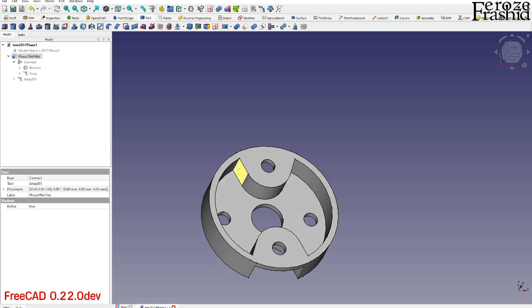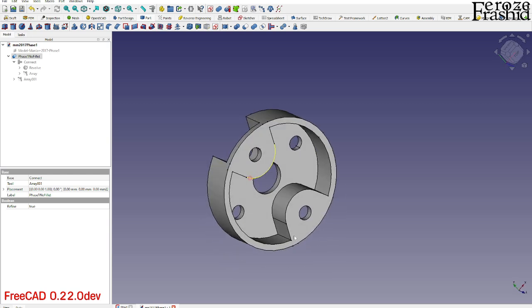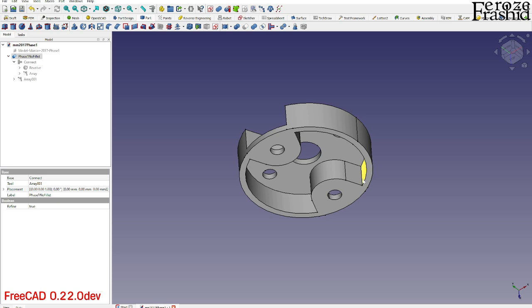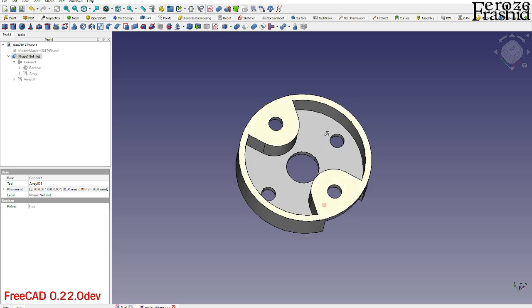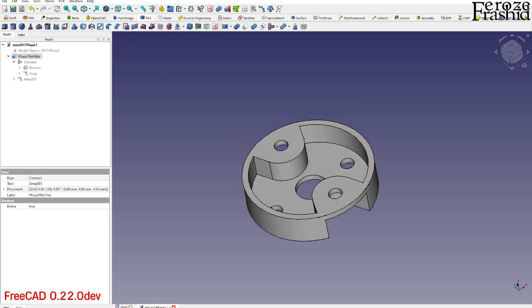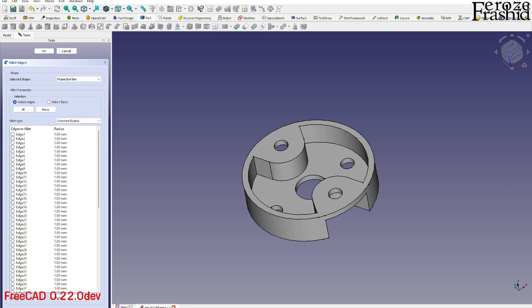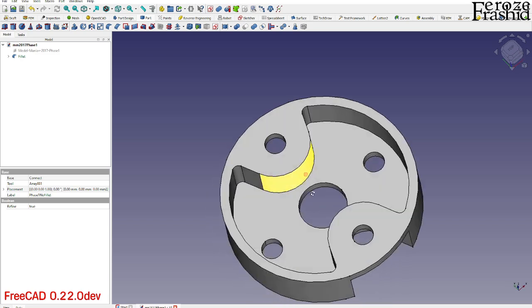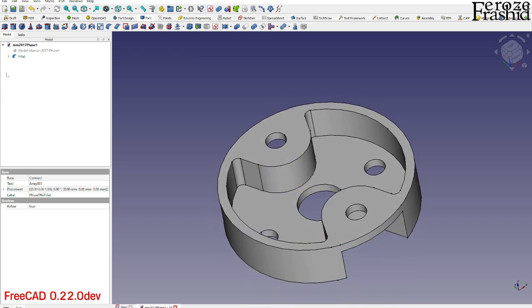a fillet. Okay. And come here, fillet, and I think it's 2 millimeter fillets all around. Yes, so make it 2. Let's make sure like we have all 4 edges selected. We have 2, yes, 4 edges selected. So we have 4 edges, made them 2 millimeter.